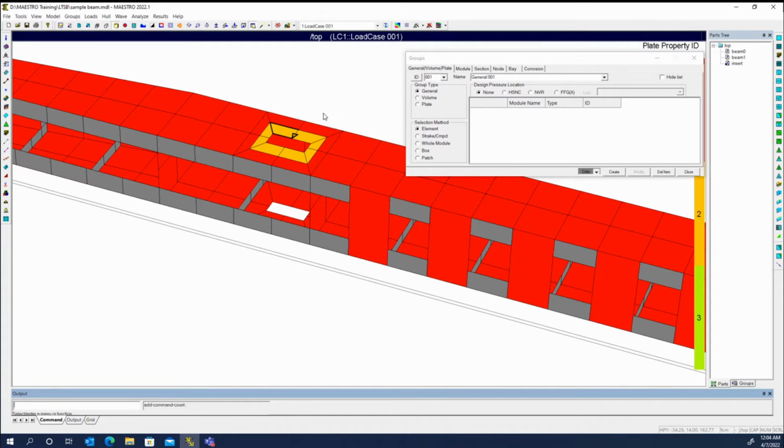that element. If you knew you wanted to match something over here in the model, you can grab all the elements in this area that you want to modify, and then grab that one as the last one and say assign same property. And that's very handy when you're dealing with beams and there's a huge list that you want to select from.